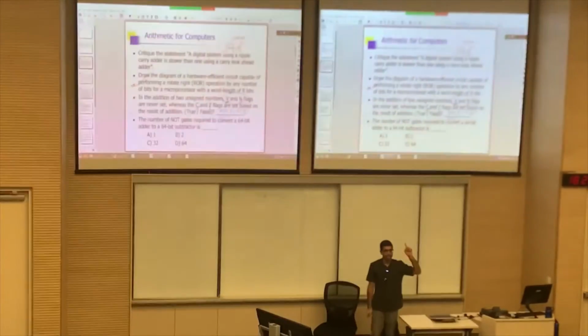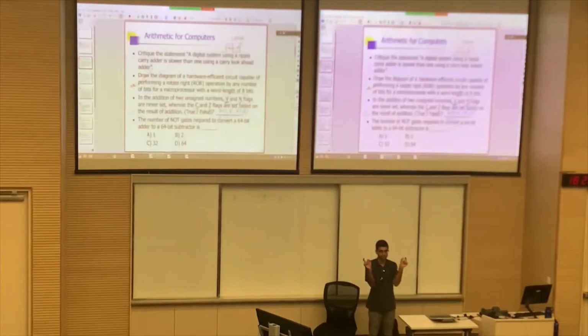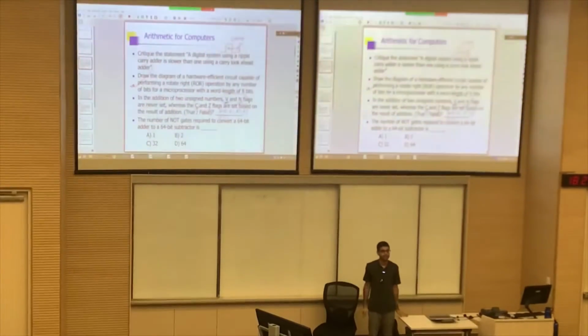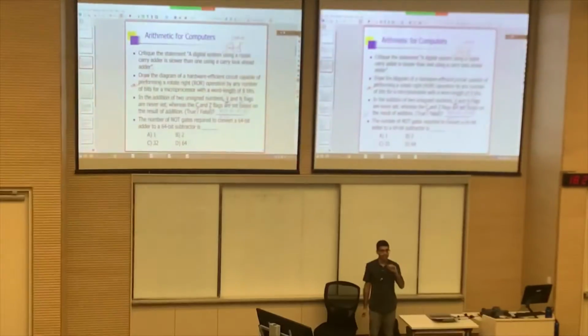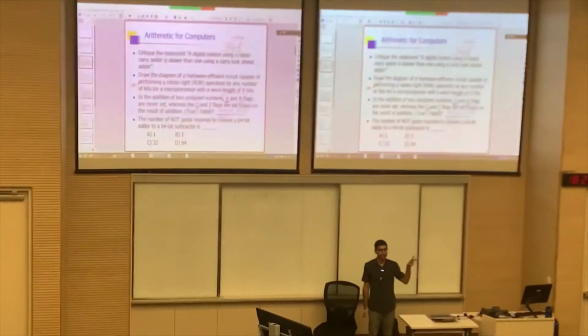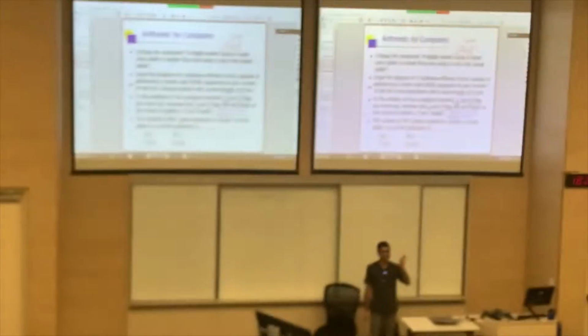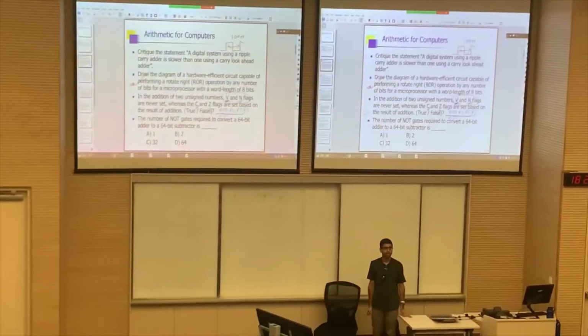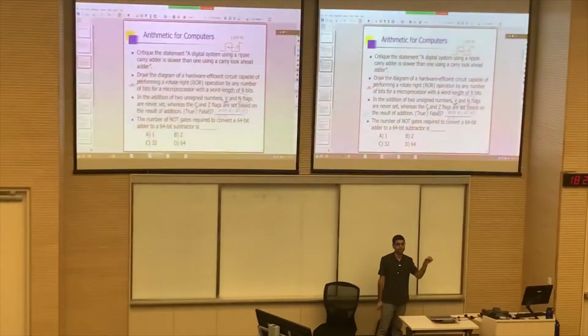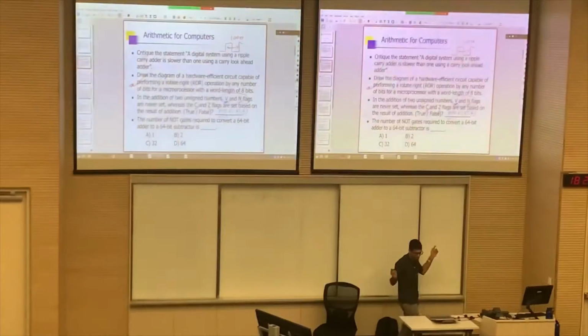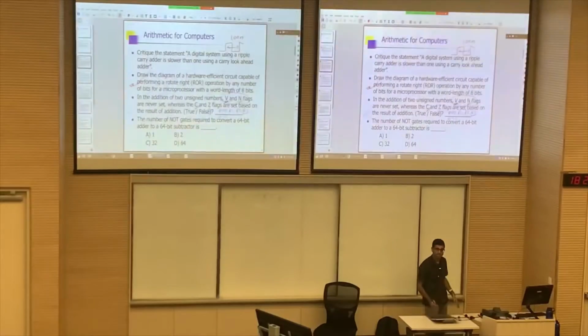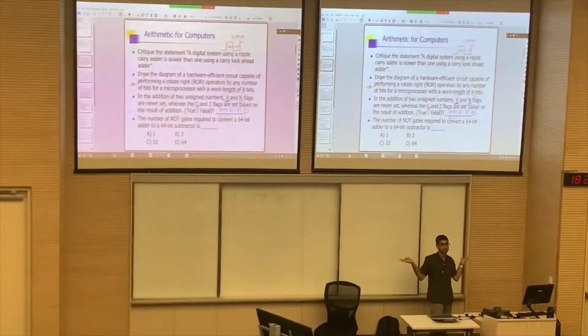If you look at the expression for GT, or the combination of flags evaluated, you will see that it uses the V flag, N flag and zero flag, not the carry flag. And V and N are supposed to be checked only for signed numbers, whereas our assumption was that R2 and R3 contain unsigned. So you are doing it wrong.